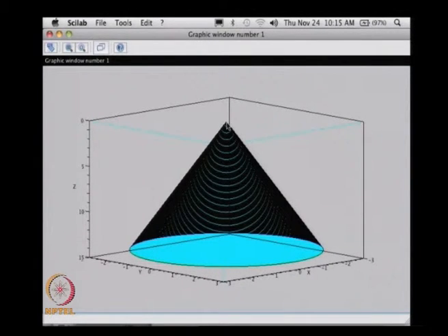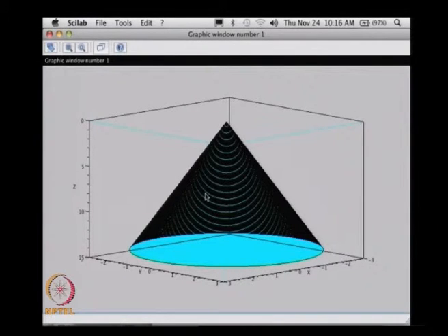But the shock wave is not going to be the two straight lines which we were drawing so far, like the two edges of the wedge. Here we actually have a surface, so for the shock wave also we will actually have a conical surface centered around this vertex.